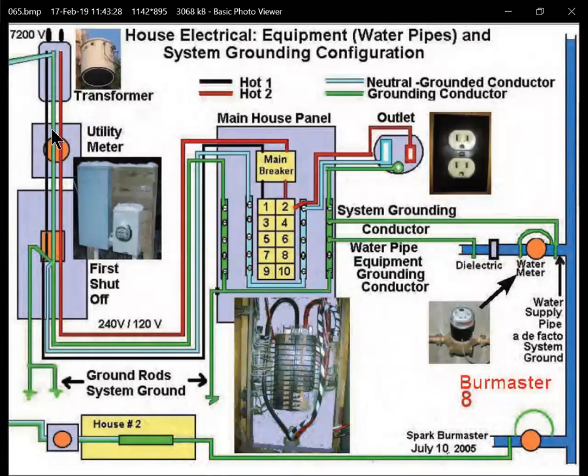And then in the world of electric codes, ground wires, which is any wire that's connected to the grounding system, use the color green. And when you see the actual wire, it'll have a green coating on it. Or the other way you can have grounding wires is just a bare copper or aluminum wire. So if it's either a bare wire or a green wire, then that means that wire is connected to